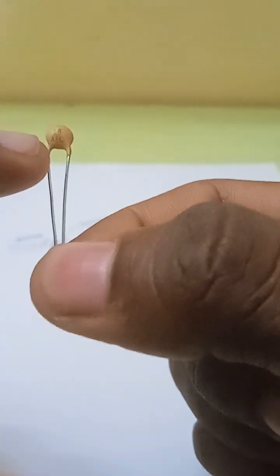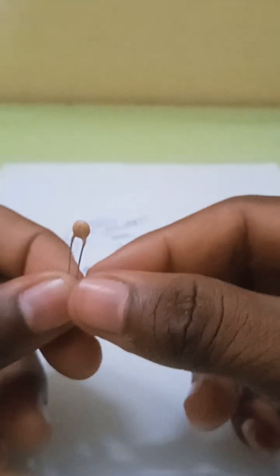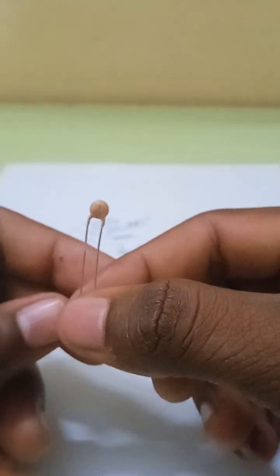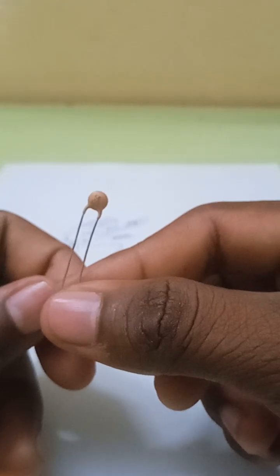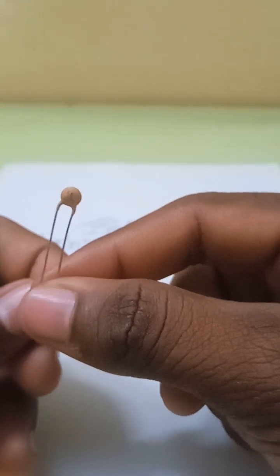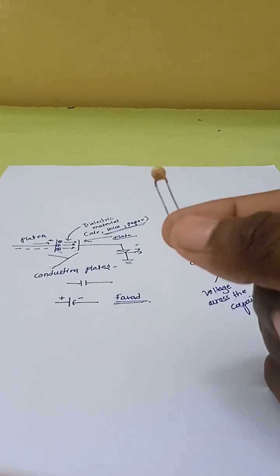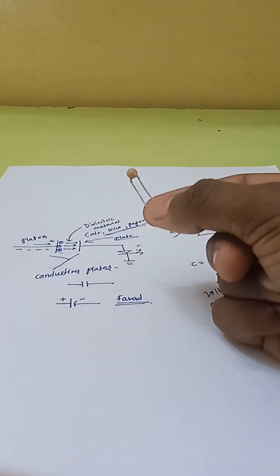Because it has something written here, which means it follows the EIA rule, the Electronic Industries Alliance rules. EIA means the default value of a capacitor is in picofarad.